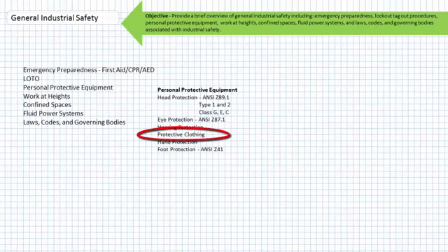Protective clothing. At a minimum, clothing should be chosen that is resistant to abrasion, chemicals, and fires. Obvious environmental considerations require that you stay warm or cool depending upon the season, but flammable clothing, or worse yet, clothing that melts when it's on fire, is not authorized on the job site. Special circumstances sometimes require high-voltage sleeves or even arc flash protection suits if involved with high-voltage switching operations.